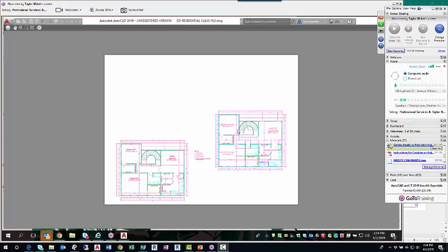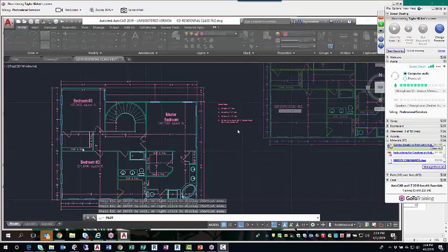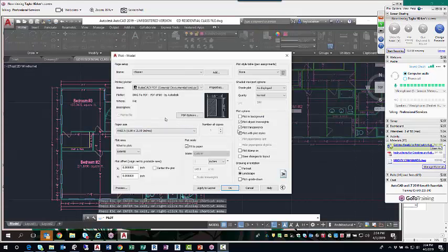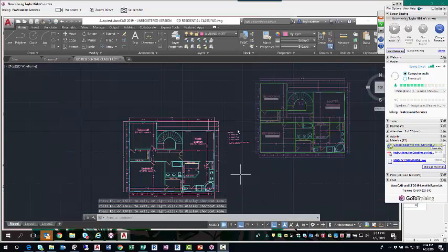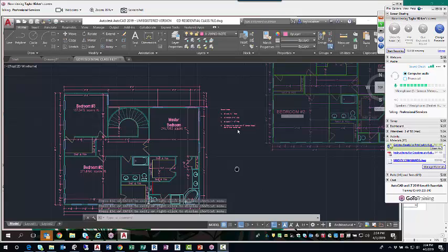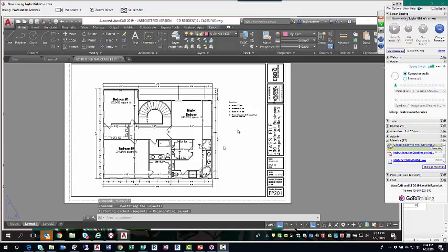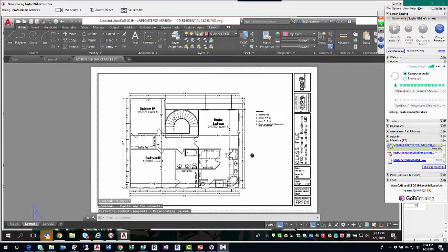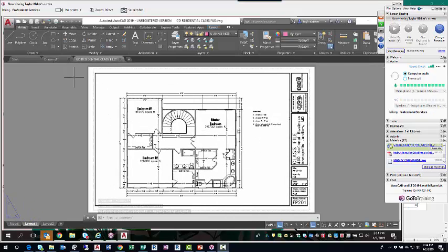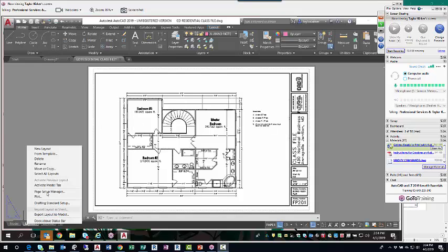Does this happen when I preview? I got you. Let's exit the preview. And then let's cancel this. Just hit the cancel button. And you could have printed that. You can absolutely print from, we're in model space right now, but if you click on layout 1 or layout 2. Okay. There you go. And then if you want, you can right click over the layout 1 tab, and from the right click menu, you could rename it if you wanted to.